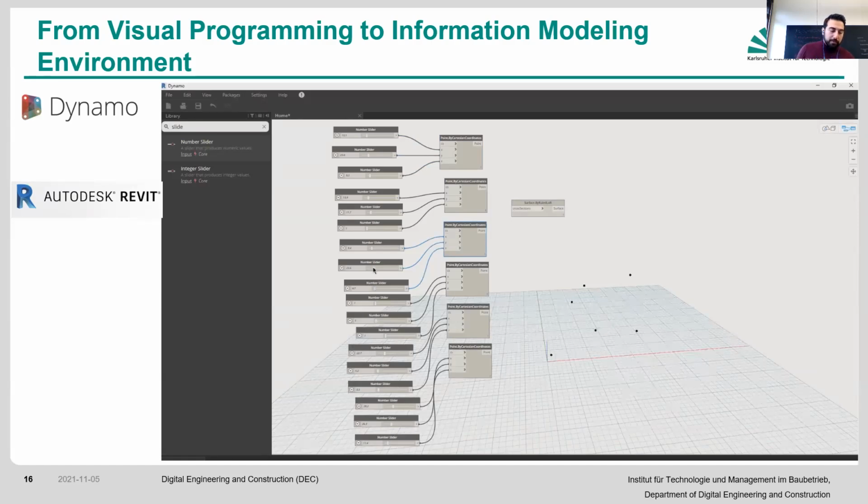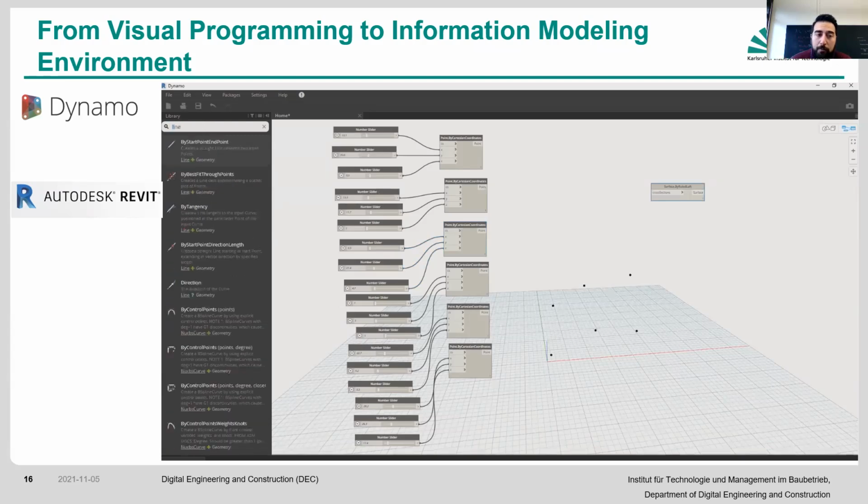So once we have this, we have to create a line between these points that we have here. For every 2 points, we create one line. So now we go to the line command, and there are various different ways of defining lines, right? We have the tangent, and different types of systems. One simple way is to have 2 points and attach those 2 points together. So we have the start point and then the finish point, and then again, the start point and the finish point there.